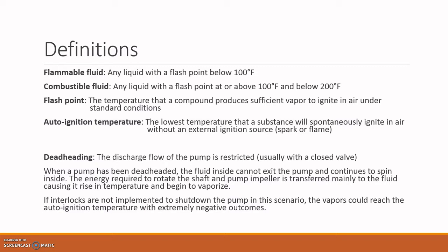And if there aren't any interlocks that will automatically shut the pump down, in this kind of scenario the vapors could eventually reach the point where the material would fully flash off to vapor, and then they could effectively auto-ignite. That could lead to some serious negative outcomes, including combustion of the vapors or, in the worst case scenario, an explosion inside the pump.